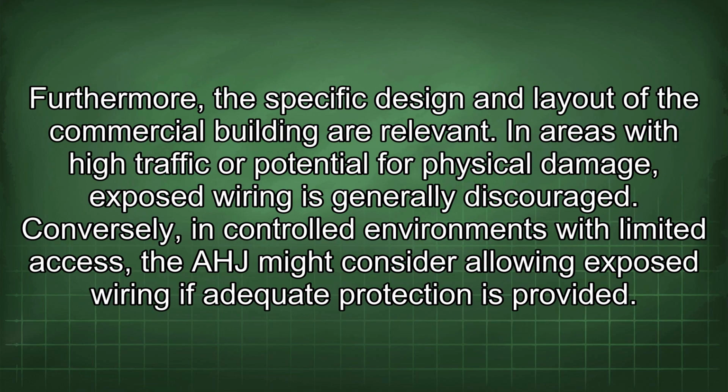Furthermore, the specific design and layout of the commercial building are relevant. In areas with high traffic or potential for physical damage, exposed wiring is generally discouraged. Conversely, in controlled environments with limited access, the AHJ might consider allowing exposed wiring if adequate protection is provided.